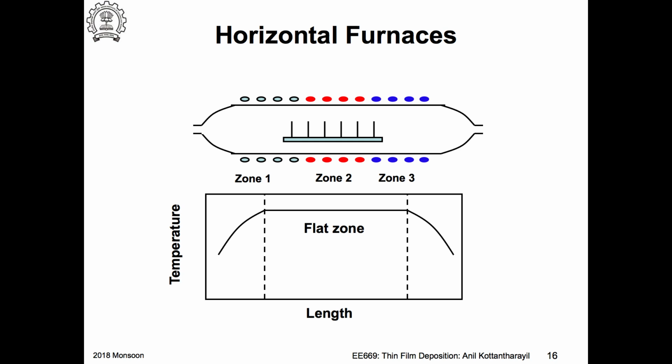But you want all the wafers to see the same temperature, so you keep three zones, meaning one example, right? So you heat this, it would actually get higher power to compensate for the losses. That also happens here at this end. So usually we use PID controllers for controlling temperature, and the PID values have to be set differently for the three zones.